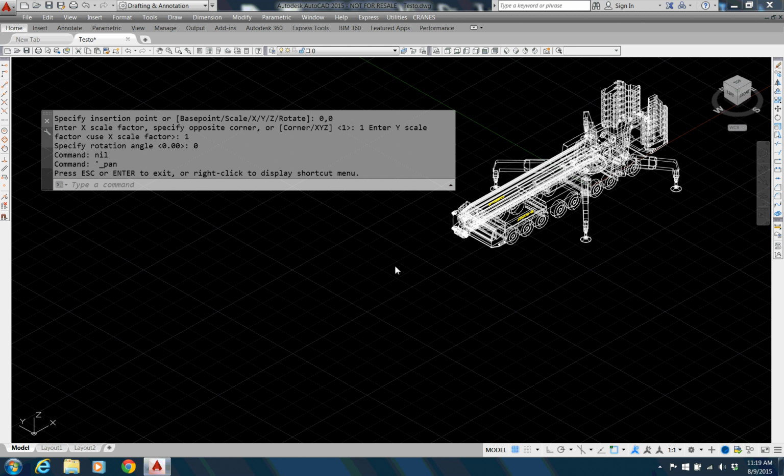Okay, now we're going to have a look at the HAV jib on the main boom for the AC 500/2. Got the crane in the environment. There's already a load to be lifted, so we're ready to go. Let's go to cranes, main, HAV fixed jib, and start it up. And we get the nil reply indicating that the executable loaded properly, so we're good.